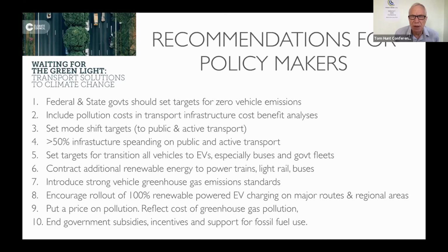Of course, most of our power is taken from home. You will be only slowly charging if you're at home generally, which is a good thing. If you go for long trips, then yes, a bit more stress on the battery. The other thing is the amount of charge you put in the car also stresses it. As you get closer to 100%, it's harder to push more electrons into the battery, and it stresses the battery a little bit more than if you don't fill it completely full. So unless you're using the full range every day, it's best to charge to, just say, 80% and leave it at that.